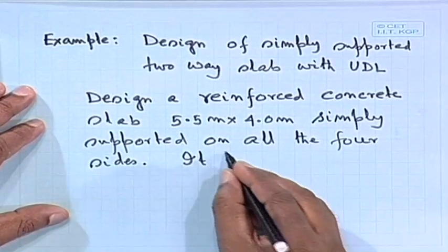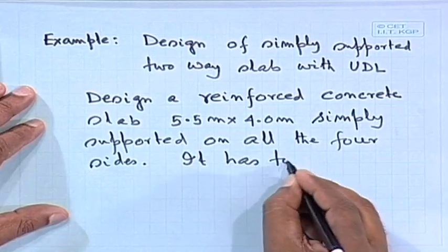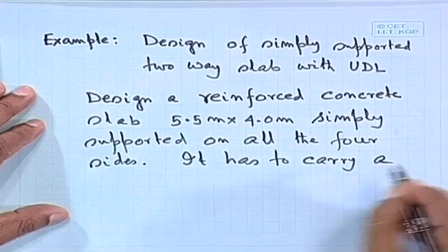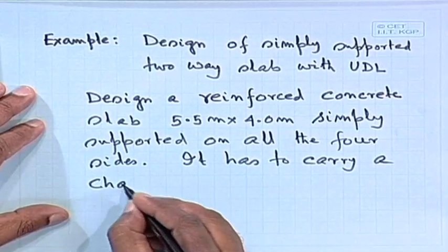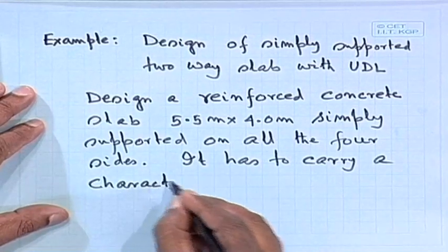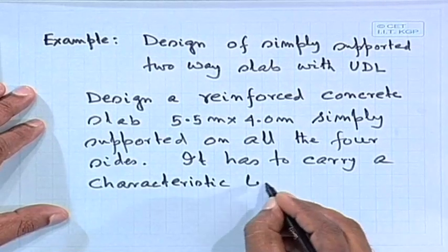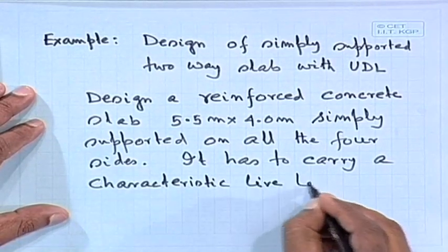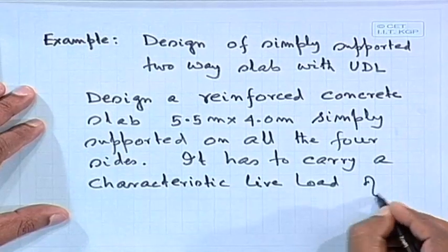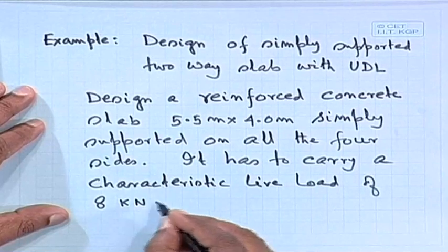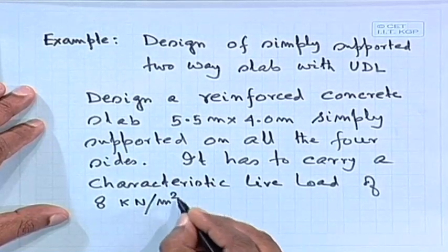It has to carry a characteristic load, let us say live load, of 8 kilonewton per square meter.